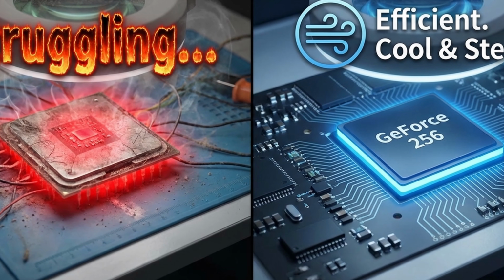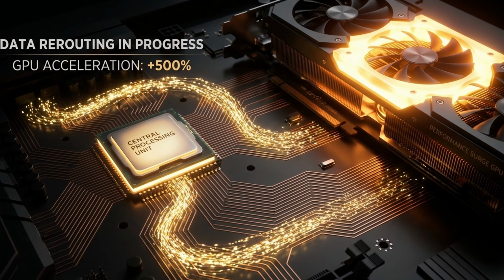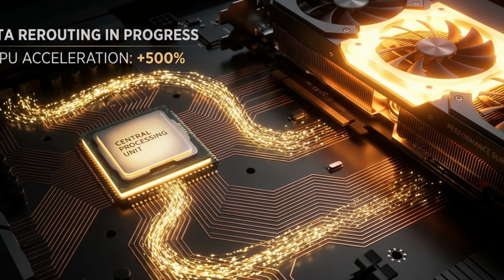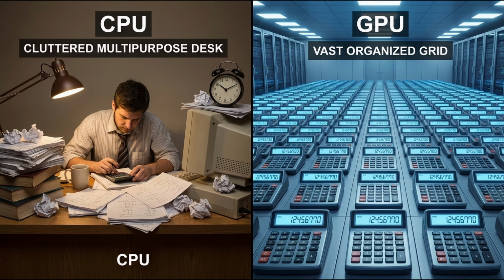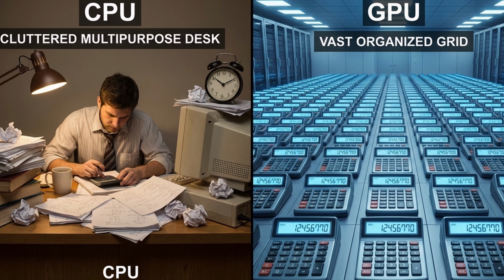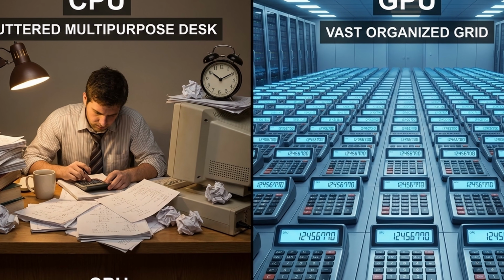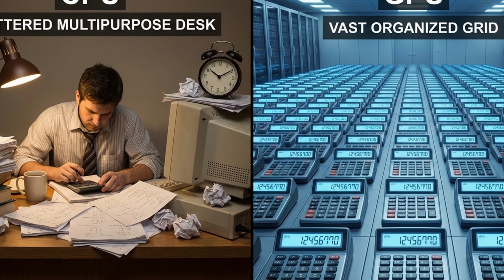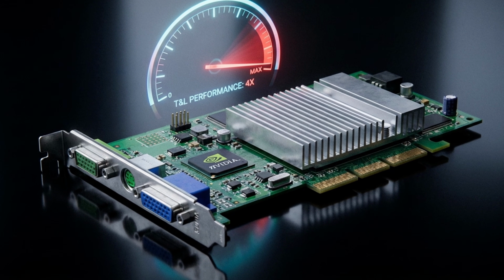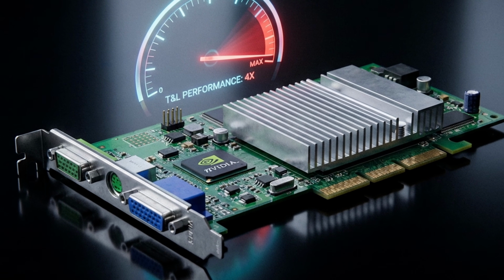a standard CPU. By moving these intensive transform and lighting calculations from the CPU to the dedicated hardware of the GPU, the industry experienced an immediate and staggering performance uplift. General-purpose CPUs were highly inefficient at continuous matrix mathematics, whereas the GPU's dedicated engines were optimized specifically for these exact floating-point calculations. Consequently, the GeForce 256 could process transform and lighting mathematics at 2 to 4 times the speed of the fastest CPUs available at the time.